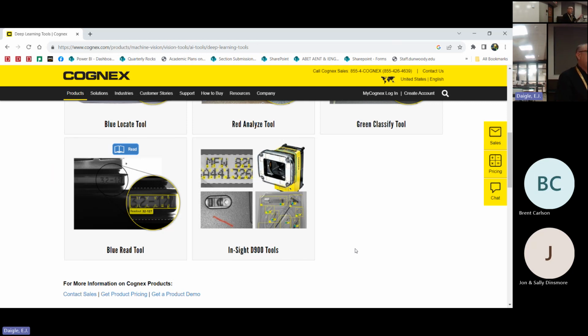That camera would be installed on a PLC system. And so the PLC would think it's part of its own system and say, hey, look, I got a Cognex camera with IO on it. I can talk to this Cognex camera. The person programming the PLC would program in those inputs that they would get from the Cognex camera. So inspection result good, inspection result bad, fill low, fill high. And then the PLC would make decisions to drive outputs that would respond to pass or fail off of the camera. So really there is no separate PC required. There's no separate server required. It's a single PLC and a single camera that can do all of that stuff.